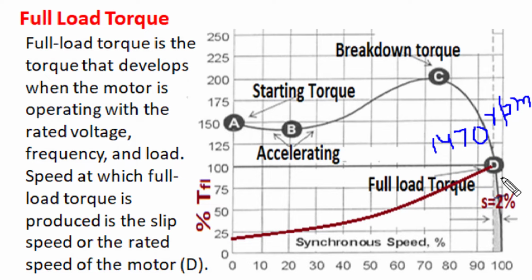is only 30 rpm. For a standard NEMA B design motor, the maximum torque developed by the motor is 2 times the full load torque, so if all of a sudden the motor torque requirement increases and even becomes about double, the motor will operate in this stable region, and if accidentally the load torque requirement exceeds the 200% limit, in that case the motor will stall as the load torque is much more than what the motor can produce, and deceleration further reduces motoring torque capabilities, and the motor will ultimately stall.